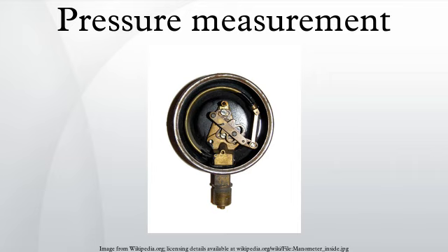In practice, a flattened thin-wall, closed-end tube is connected at the hollow end to a fixed pipe containing the fluid pressure to be measured. As the pressure increases, the closed end moves in an arc, and this motion is converted into the rotation of a gear by a connecting link that is usually adjustable. A small diameter pinion gear is on the pointer shaft, so the motion is magnified further by the gear ratio.